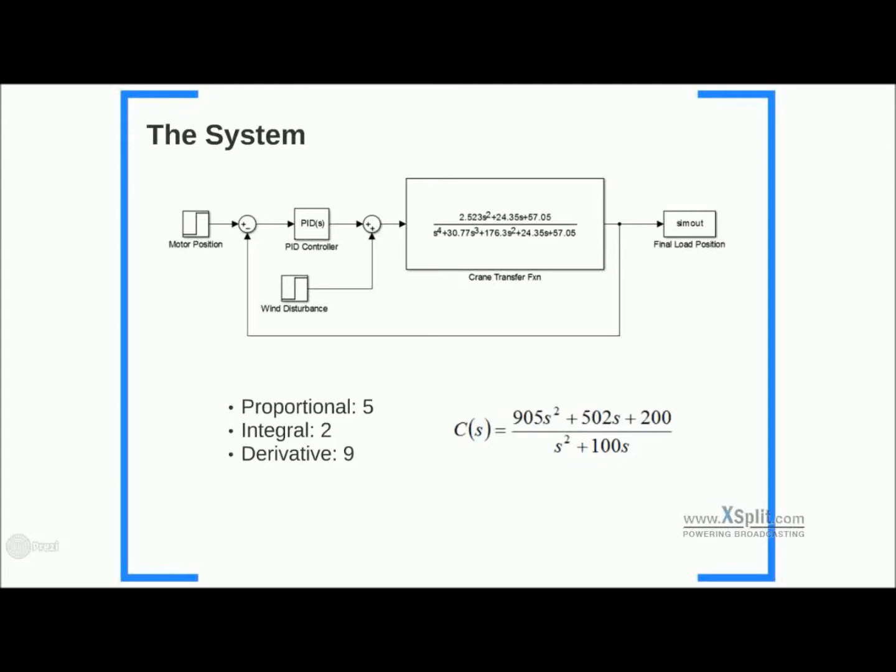Adding in the derivative term decreased our overshoot to meet our requirements, and as you can see here, we ended up choosing a couple of specific values for those gains. These are all sort of driven by initial mathematical calculations. Then we iterated through in MATLAB to come up with values that would actually meet our specific requirements. We can see here the proportion between the different gains that we have. We had a lot of trouble with our percent overshoot, so our derivative gain is really high. And that also helps with the settling time, which is another one of our key concerns.